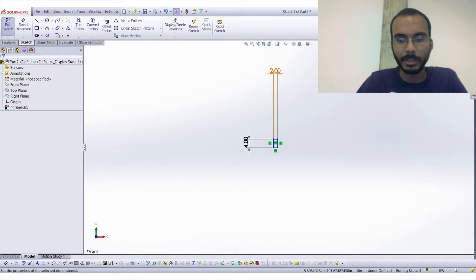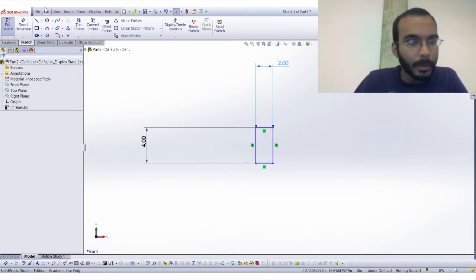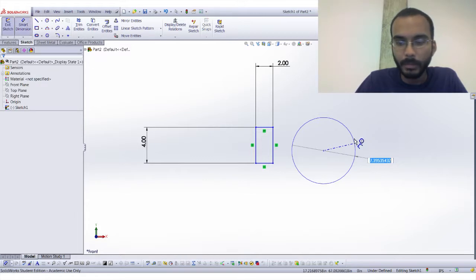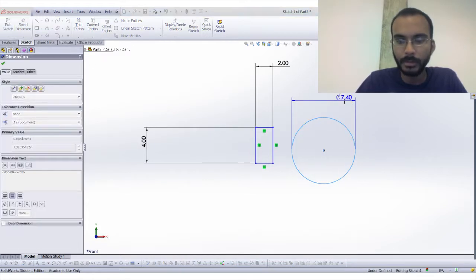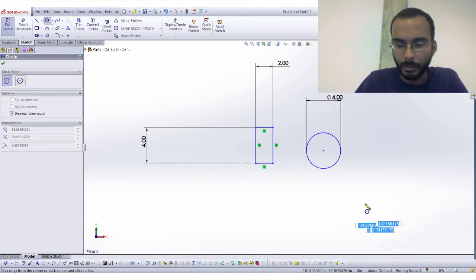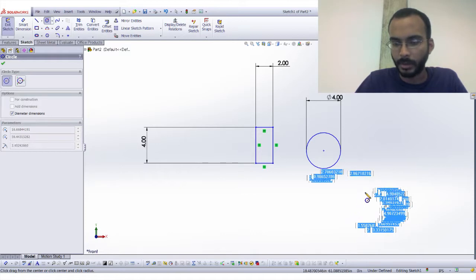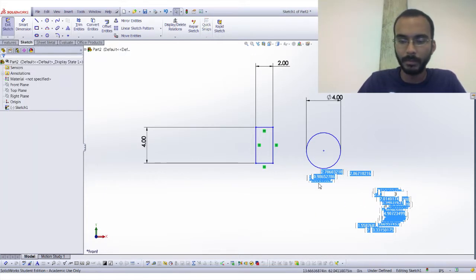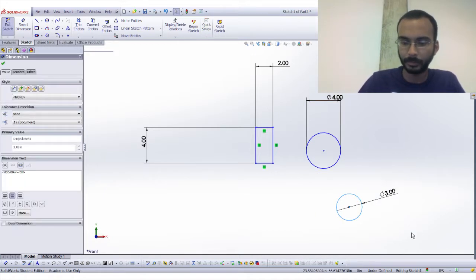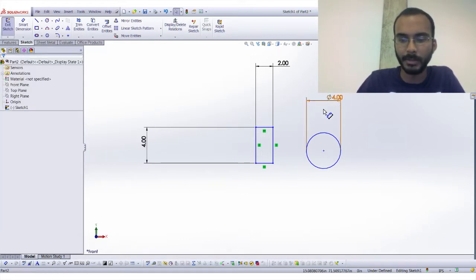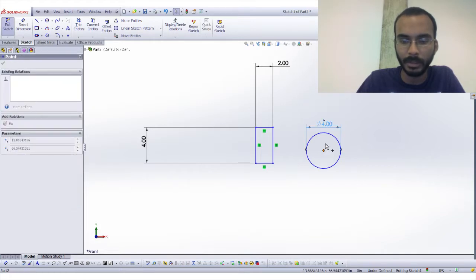And now you can change the dimensions pretty quickly. So you can do that with all things. If you draw a circle, you can then dimension that circle. One of the options you can set up is to input dimensions as you go. So as I'm drawing this circle, it gives me a little box that I can type into, and then I can just hit 3 enter, and now that circle's fully dimensioned, and I don't have to do Smart Dimension on it every time. It's normally the default option, but it's not always. If not, don't worry too much about it for right now. We can change that setting later.